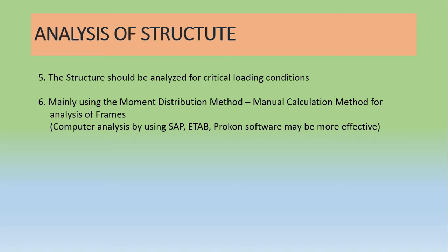Mainly using the moment distribution method, which I will teach you, to calculate the bending moment diagrams, we want to get the maximum shear forces and bending moments. So the moment distribution method is mainly used for subframe analysis, and computer analysis can also be used to get the maximum bending moments and shear forces.